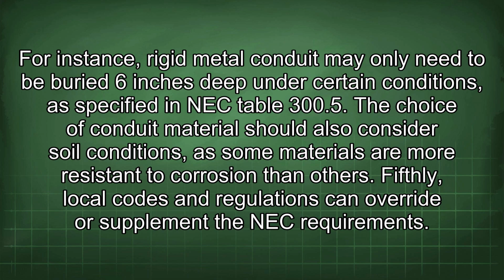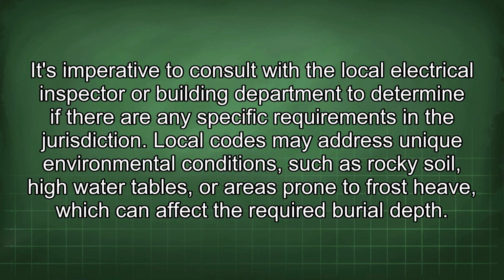Fifthly, local codes and regulations can override or supplement the NEC requirements. It's imperative to consult with the local electrical inspector or building department to determine if there are any specific requirements in the jurisdiction. Local codes may address unique environmental conditions such as rocky soil, high water tables, or areas prone to frost heave, which can affect the required burial depth.